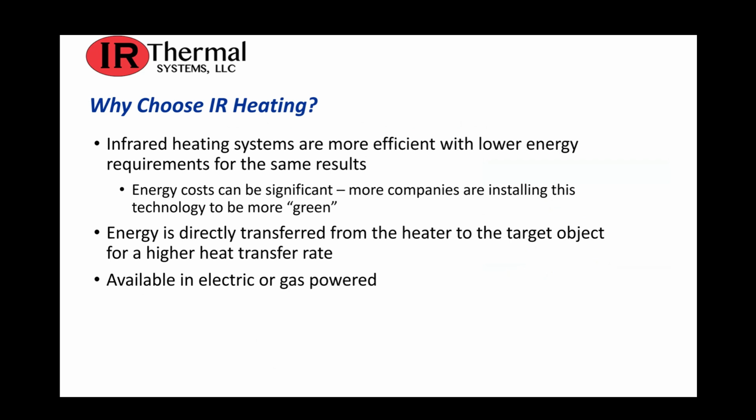So why choose infrared heating to begin with? Well, infrared heating systems are more efficient with lower energy requirements for the same results. So today, energy costs can be significant. More companies are installing this technology to be more green. The energy is directly transferred from the heater to the target object for a higher heat transfer rate, and they are available in electric or gas-powered versions.